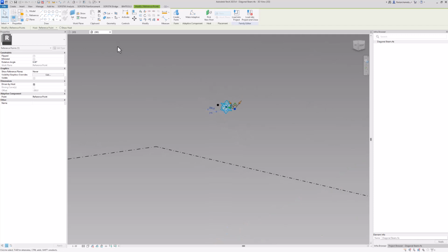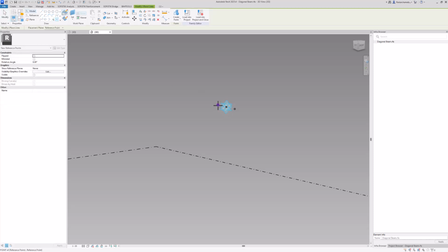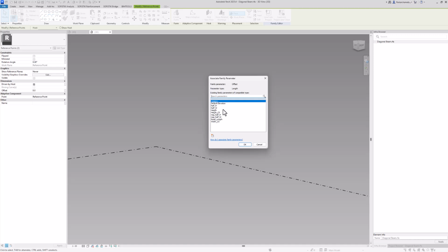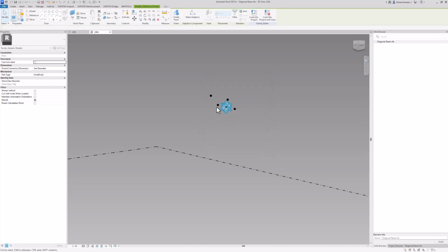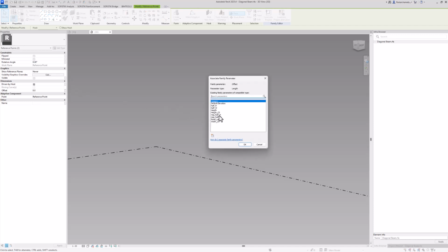Now it's just the height that we still have to assign here to create our parametric rectangle. So I select this plane, create a point, select this plane, create a point. Actually, I can already create 2 points at both planes because 2 of them are going to be positive, 2 are going to be negative. By clicking Control, I select multiples and I assign half height as well as negative half height.